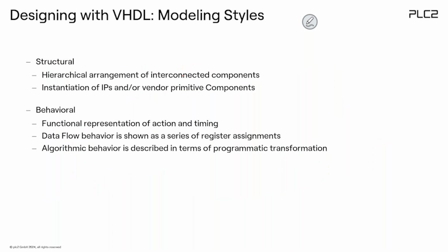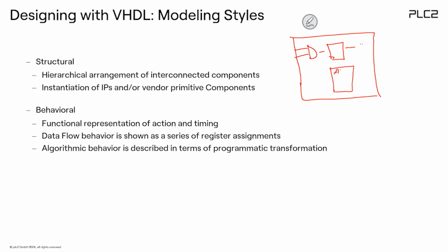And this is maybe the most important information here. We actually have two types of design when using VHDL. We can do structural, and this means we could use primitive components like gates or flip-flops and connect them somehow, or we can use hierarchical elements to build something. This is called structure, because there's no behavior at all. We just place this element and this element, and connect them somehow. It's called structure. Behavioral is something different.